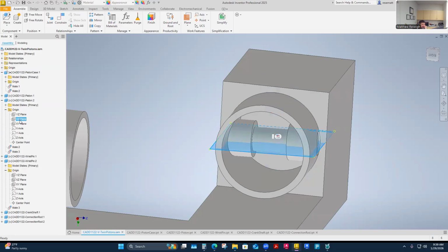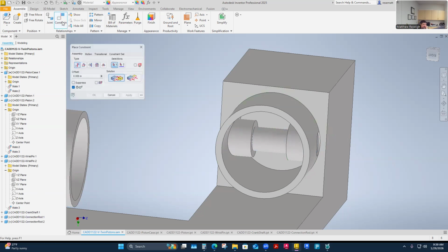This one doesn't do me a lot of good that direction. It would stop the pin from rotating potentially, which I don't want to do yet either. I just want to center it, and I'm okay if it rotates. Right now it rotates because it's just got an axis alignment, but I don't want it sliding back and forth because I want it to be centered in that piston. So this is why I chose this next constraint as this plane, which is weird.